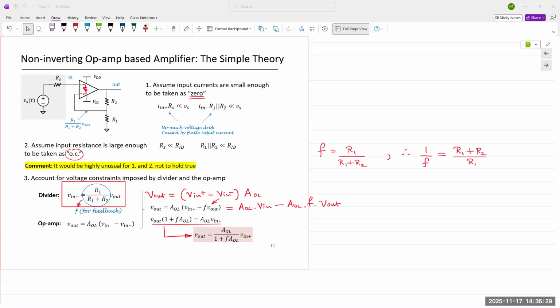It is defined by the manufacturer's data sheet. The question being asked is, what are reasonable values for AOL? Well, the values for AOL would be found on the manufacturer's data sheet. In real life it is not typically infinite, but very high, 100,000 would say, at least 10,000 or 50,000 and higher. And then, of course, there are also frequency limitations. The op amp does not have infinite bandwidth. As the frequency increases, the op amp gain starts decreasing. So there is always an upper limit, real life considerations.